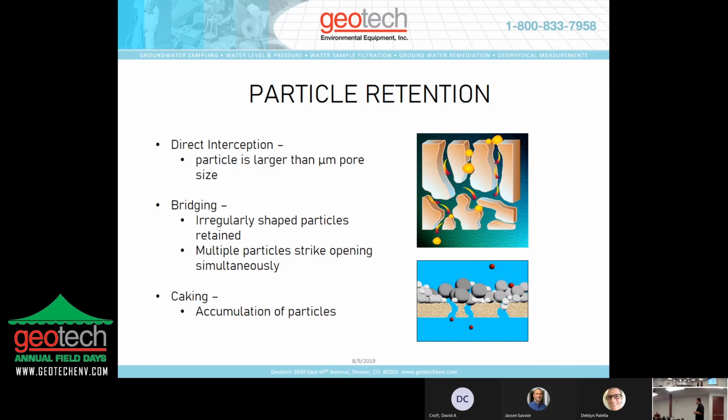Well, your filter is clogged, it's plugged up. We'll have customers that will call and say, hey, your filter blew up, it came apart, right? Well, what happened? Tell me a little bit more about what you were doing. Well, we were flowing through the filter, water was flowing great, it stopped. So we cranked up our electric submersible pump to increase our flow rate, just over pressurized the filter and just separated the two bonded pieces.